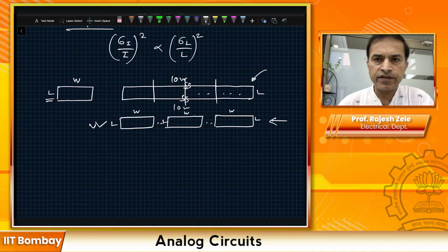You don't really lay out. Let's say there is one transistor called transistor A, and then let's say I have transistor B, which, in this particular example, let's say there are 4 transistors, 4 units of B, right? So this is B. Then you really don't lay them out next to each other like this, because what will happen is, these guys are on one side, this guy is on one side. The statistical variation and also the slope of the oxide would be very different. And sometimes A could be a lot bigger than the unit size of B. So what you do is you do something called common centroid layout.